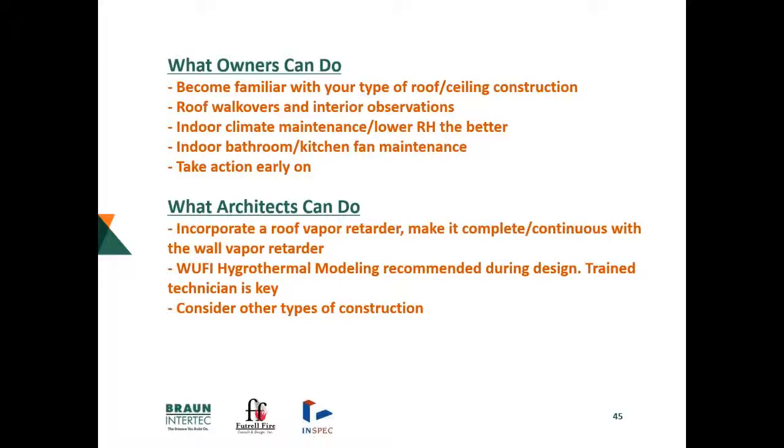The other thing I think is venting, whether it be dryers, kitchen vents, bath vents. We are talking about the main top floor that we're having the problems. But instead of running them out to sidewalls, it might be a better choice to just go straight up with them. Yes, you have another roof penetration, but you can enclose those things. I think that's another good idea as well. But you do have to be careful with how many you are getting on a roof and causing concerns with drainage and other things. But certainly organized, planned out, maybe even centralized, making some sense of those penetrations is a good option as well.